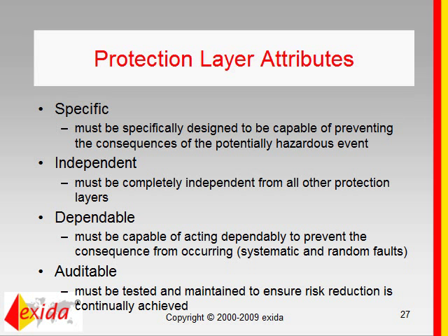So basically the layer needs to be always there. And then lastly, we must be able to test the layer, which is going to be a little bit difficult, for example, on a rupture disk, but you could argue that the manufacturer tests 1 out of a batch. For your relief valves, it's a little bit easier. They typically do, or you're typically required to do a pop test every 3 years, at least here in the U.S., as part of an ASME standard. So you have that aspect at least taken into consideration.